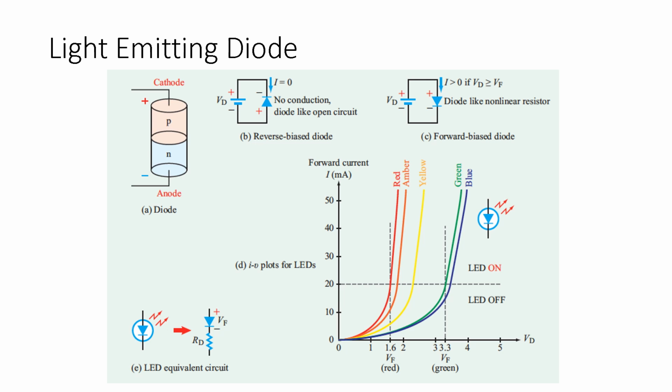So a lot of info on this slide, a lot of cool stuff about LEDs. I'll post another link or two if you want to read up some more on your own about how LEDs work. And we're going to do a lot of labs with them too, because LEDs are a really nice way to show if your circuit is working, because you get to see visual feedback immediately if you've put your reverse bias diode in, or your forward bias diode, or if you're looking for a certain amount of voltage. You can even use LEDs, if you're kind of clever, as a very simple analog way of showing voltage. Because, again, they each have a different forward voltage.